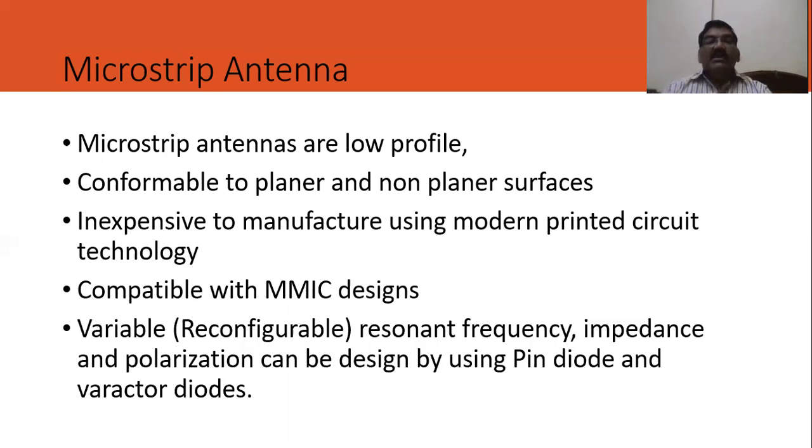And the most important advantage of this antenna is that it is a reconfigurable antenna. What does it mean? We have various parameters of the antenna that we may have discussed. You may have the frequency, that is the resonance frequency. One antenna has the resonance frequency at this, and another is this. Suppose I want to use a single antenna for two different applications, but not at a time, at different times, maybe on a time sharing basis. Then this same antenna can be used for different frequency applications. This is called the frequency reconfiguration.